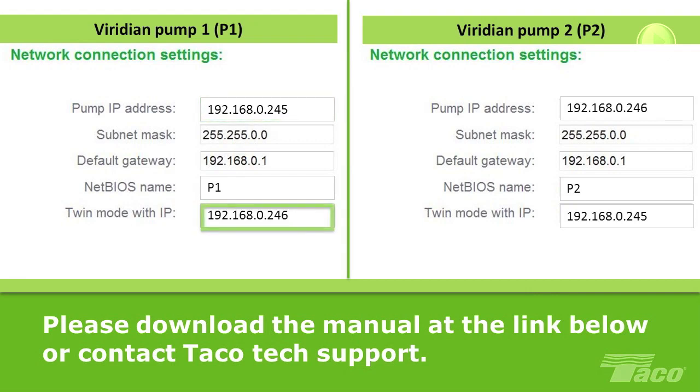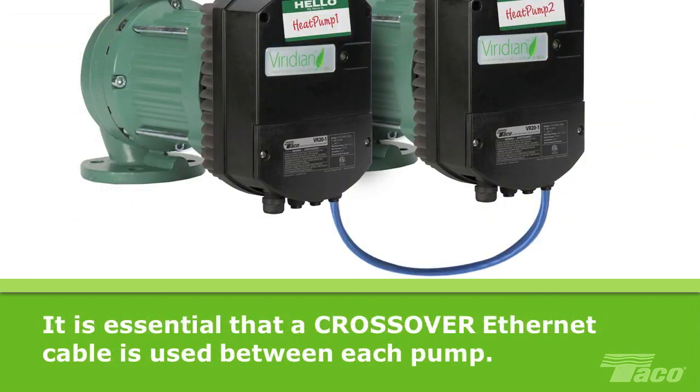The IP address of P2 would be changed to 192.168.0.246, and its twin mode IP address would be 192.168.0.245, or whatever IP address that has been assigned to P1. Please note it is essential that a crossover Ethernet cable is used between each pump. Click Save to confirm the changes you've made. You have now assigned a unique IP address to another Viridian pump.